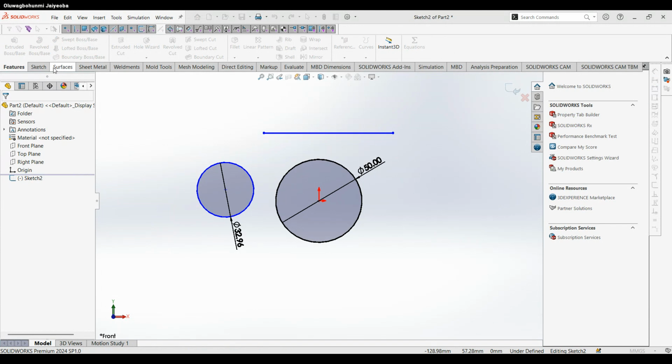We call them global variables. Click on the first box under global variable. Let's say A is equal to 20 millimeters. Type in A here and press enter to take it to the value. So I type the value of my A variable as 20 and press enter. So I have set a particular value to my A variable.